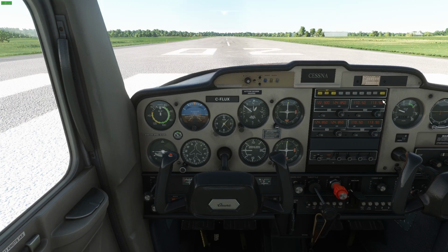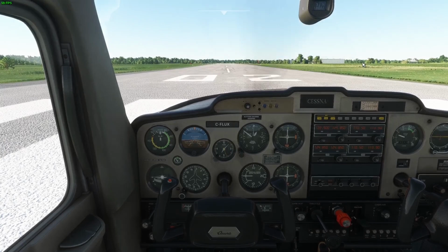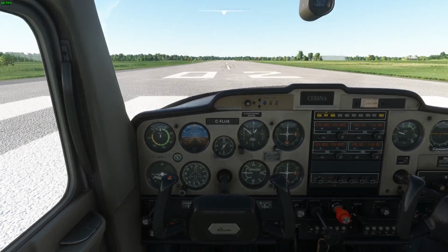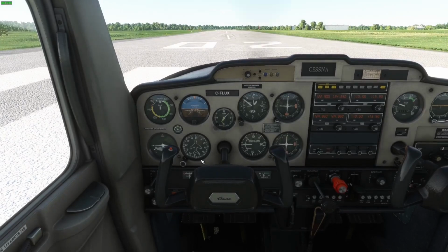So since we're pointing at the heading of 20 degrees, 020, we check on the compass. The compass will spin during turns and descents, so we use the mechanical gyro compass set to the compass because it stays stable. So we're setting at the right heading.